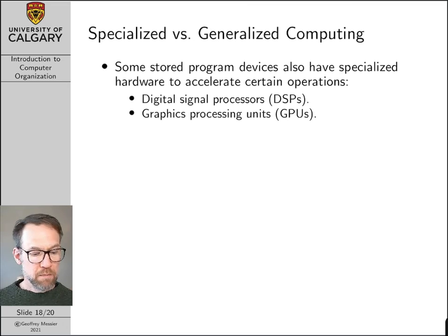And so another example are DSPs, or digital signal processors. DSP chips, again, have a bunch of specialized digital designs or cores within the chip that are meant to accelerate things like Fourier transforms or filtering operations, but they still use the stored program model. So you still write a program for these things, and the program determines what data is fed into this special digital design, and to a certain extent what operations are performed on the data.